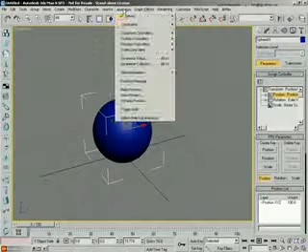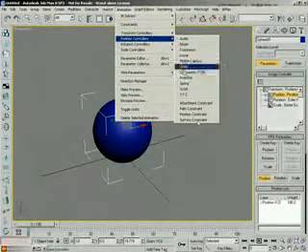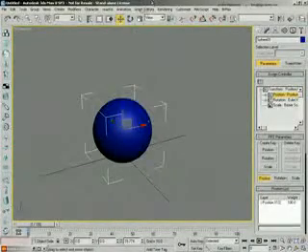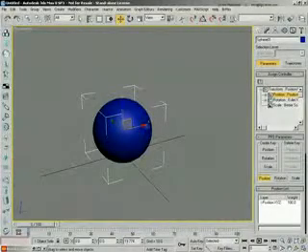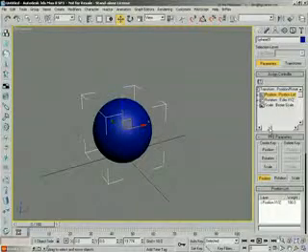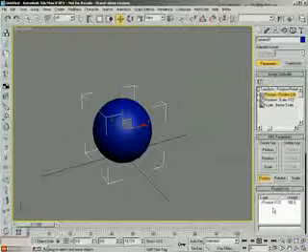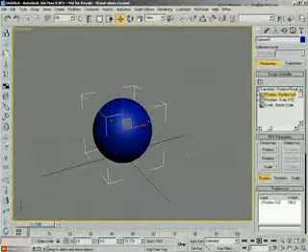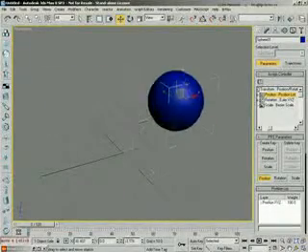Now traditionally we've been using the animation drop-down list, which is where you can get to all the same controllers. And so that's what we'll be using because it's a little bit easier and it handles a couple things for us automatically. But just notice right now that down in the lower right hand side where it says position list, it currently says position XYZ. This basically tells Max that we can freely move it